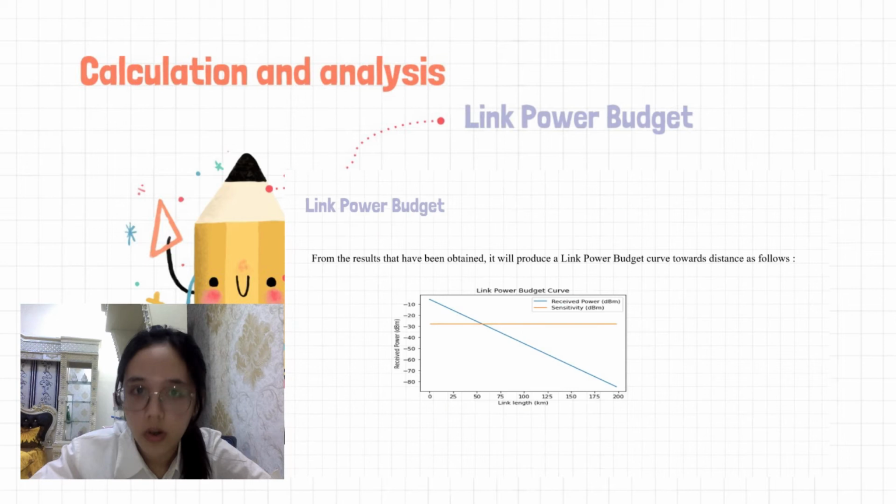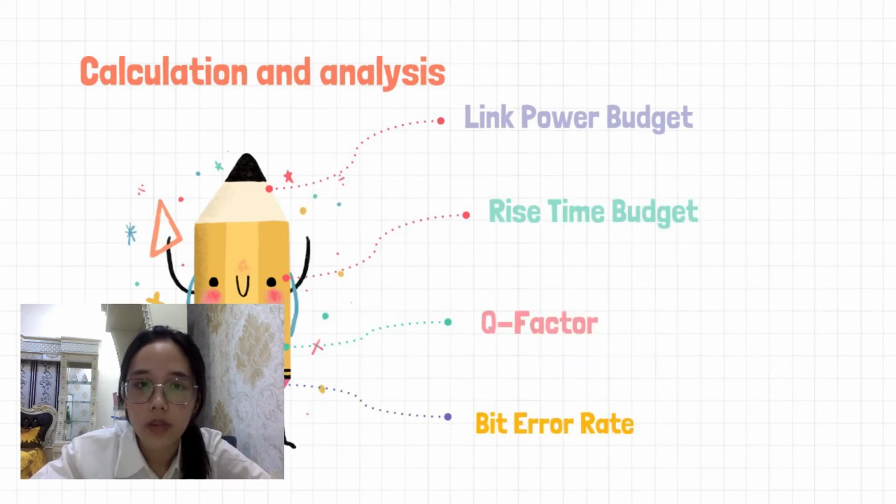From the curve, we conclude that the farther the data transmission distance, the more the acceptance level decreases. It is caused by attenuation of 0.5 dB per connector, attenuation of 0.5 dB per splice, and unexpected attenuations when sending data over a long range.